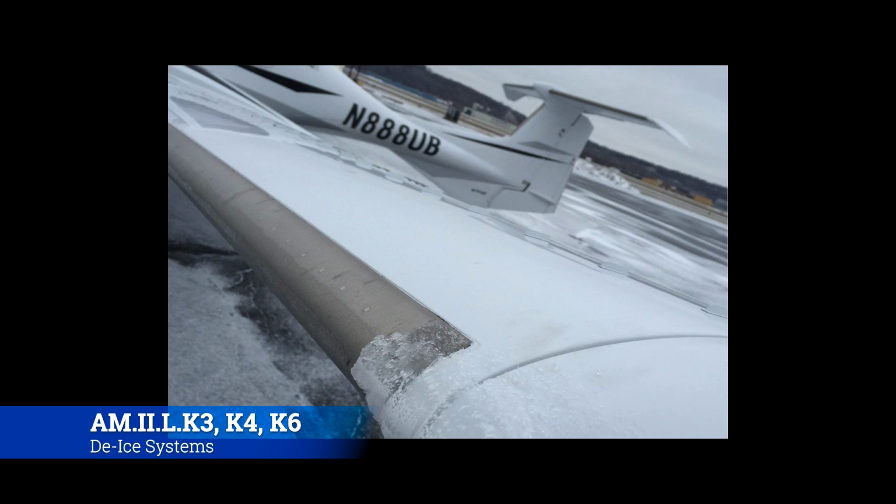Effectively, the fluid comes out and is very sticky to the wing, and it provides a layer of fluid to prevent ice from forming on there. This is extremely effective at melting ice, and extremely effective at preventing ice from going onto it. The challenge becomes keeping the TKS fluid on the wing for the length of time that you're flying through IMC conditions. Generally speaking, you don't have enough TKS fluid to get to where you're going, so this is kind of a last resort sort of system.